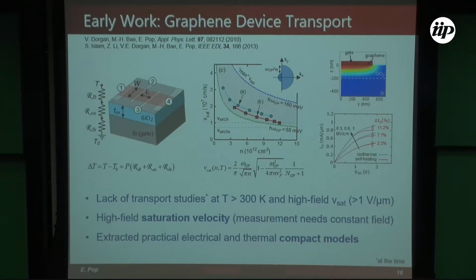So if you're familiar with drift velocity of electrons or holes in a semiconductor, which I'm sure you all are, if you go to high enough fields, the drift velocity doesn't go to infinity, it just saturates at something called the saturation velocity, which in silicon is about 10 to the 7 centimeters per second, right? This has been very well known in silicon since the 1950s. That's when the first measurements were done, we found out when we were digging through the literature. Germanium was measured a little bit later, but about the same decade, I think.